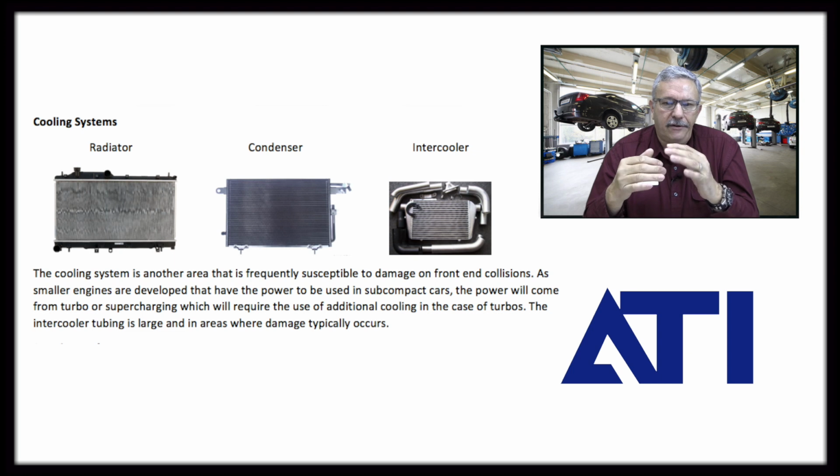So we've got to make sure if we have any kinds of situations where that could be the case, we want to make sure that we're flushing, we're cleaning the system out. It's called a nitrogen flush, where we're blowing everything out of the system. Then we make sure that all the filters are replaced and all those processes are done. Each manufacturer has very specific processes that have to be followed, but these are typically mechanical processes.